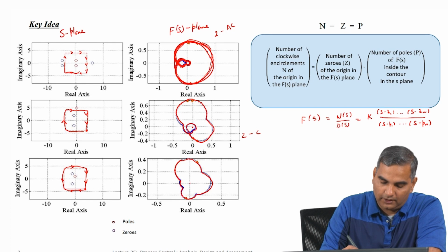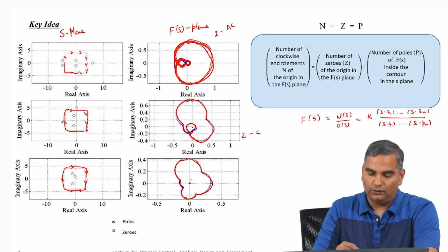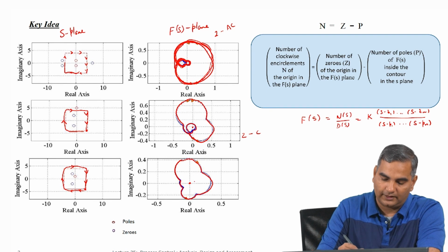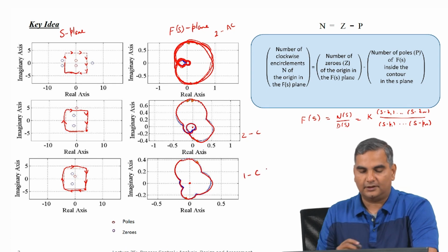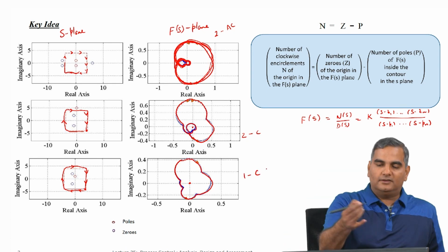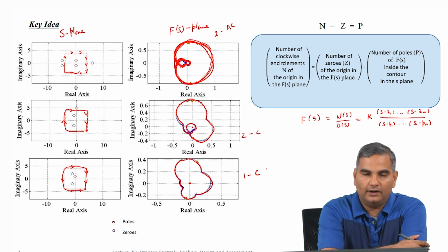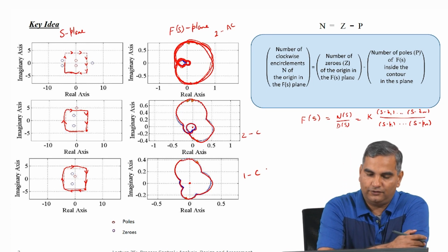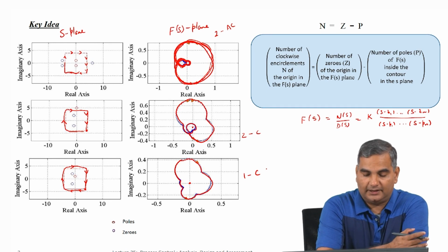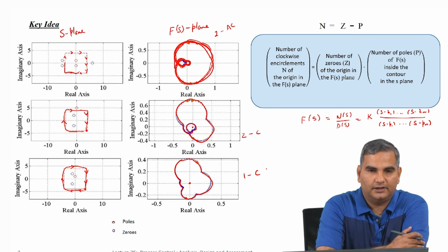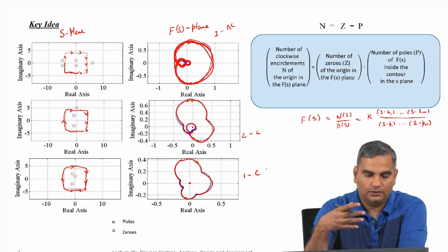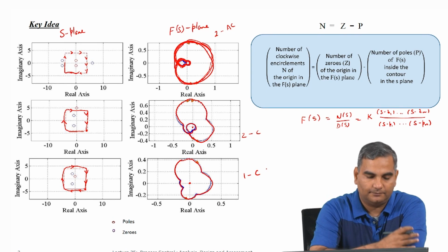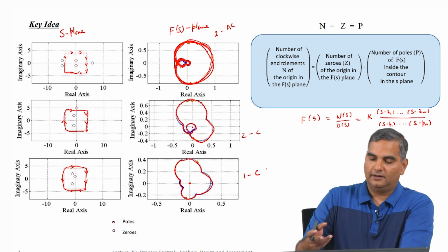And now again let us plot; the origin is inside. Now, if you notice this, starting here I go clockwise and I have made only one encirclement of the origin in a clockwise direction. So, one clockwise encirclement. Okay. So, now you might ask, why is it that sometimes in the f(s) plane I have one encirclement, sometimes 2 encirclements, sometimes in the clockwise direction, sometimes in the anti-clockwise direction, while I am always having my contours in the s plane in a clockwise direction. Okay. So, the result that puts all of this together in a single statement which handles all of these cases is the following.